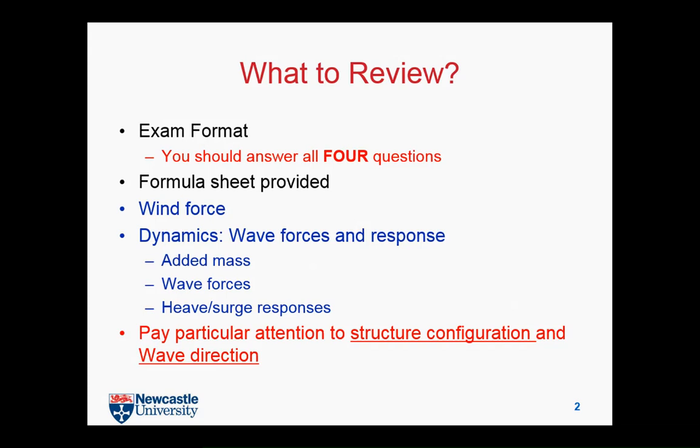And when you estimate wave force, we have estimations for force, and for the corresponding motion. For motion, we have heave and surge, because we always assume a 2-dimensional problem, so you can only have heave, and you can only have surge.